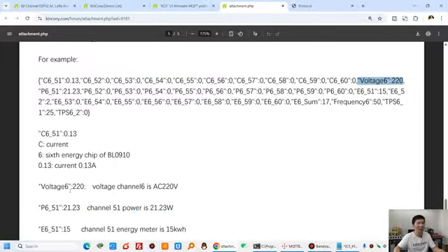That means because we have 6 channel voltage detect ports, voltage 1, voltage 2, voltage 3. And for single phase, you can see I have connected the 6 with the L, and the neutral line also connects with the N. So this detects the voltage of the single phase. And if you use 3-phase power, you can connect L1, L2, L3 to A, B, C phase. So that will show the different phase power, different phase voltage.